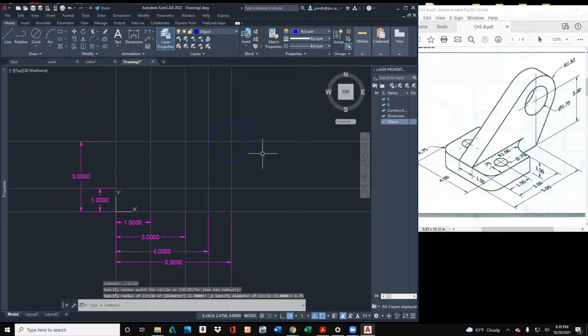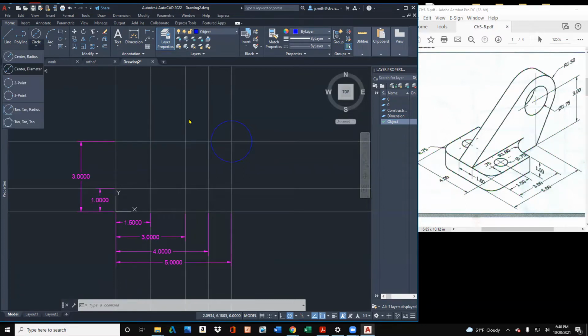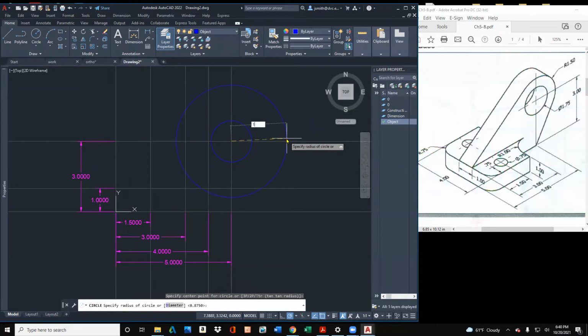All right, and then I will do the outside radius, which is 1.5 from the same point. Radius, this is going to be 1.5. Enter. Then I'm going to take this line on tangent to this intersection here. It said it's tangent, so that's good. Push enter. I'll do it again, going from here to the tangent there. Push enter, and let's just go ahead and trim that.